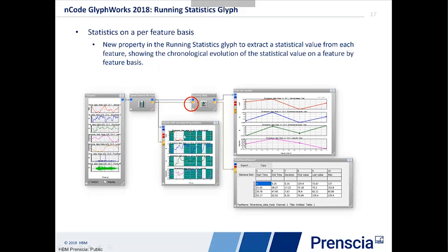So no longer relying on the time vector. So you got a choice now. You can do such statistics. The interesting bit here is this time series output showing you the stats on a section-by-section basis. You can continue the analysis. You can do a histogram saying, for instance, how many times the maximum speed exceeded, or the maximum engine temperature. You can bin that in a nice histogram. How many times has it exceeded this value every time? The brake pedal, or you can imagine all sorts of analysis based on events like that.